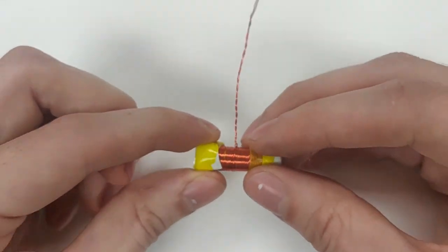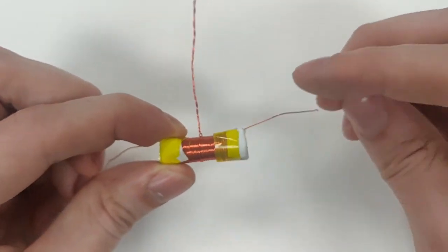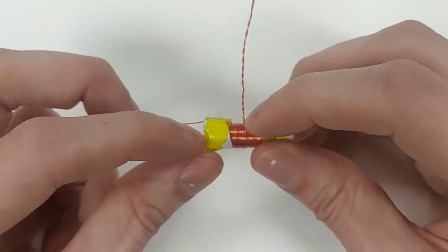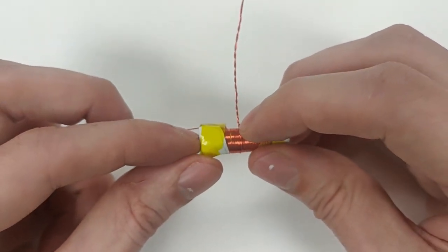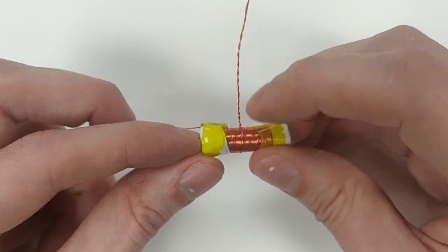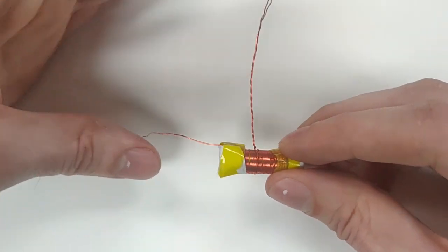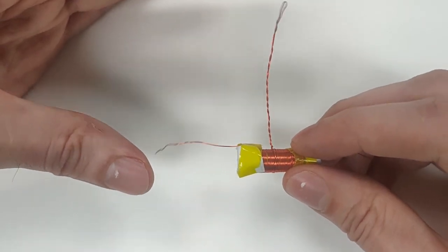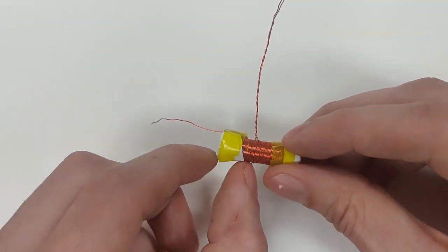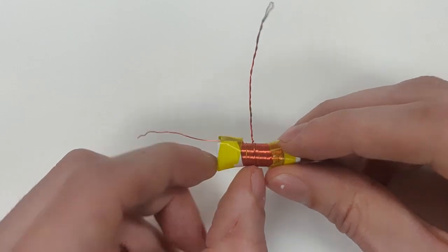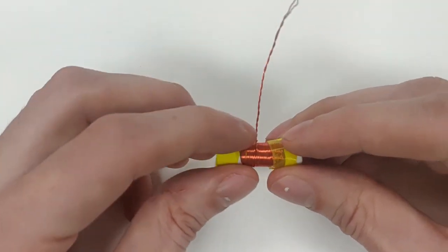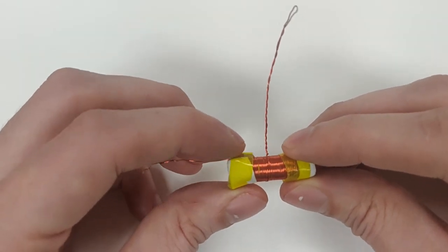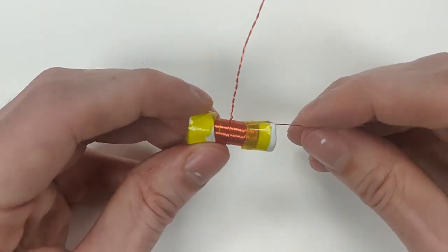And we're going to use this in the experiment to show how we're effectively changing the size of our inductor. If we attach it into our circuit from one end to the center tap, we're effectively only using this much of the inductor. It also has some other purposes in the final radio circuit as well.